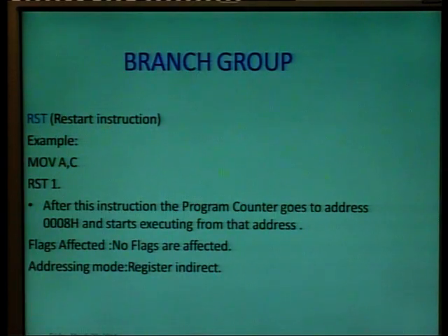RST, restart instruction, they are sometimes also called the software interrupts. After this instruction, the program counter goes to the address 008 and starts executing from that address. No flags are affected.